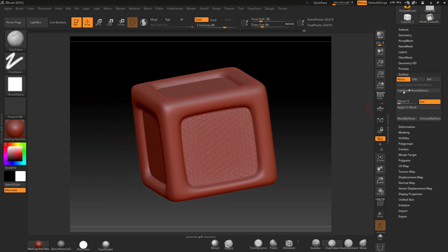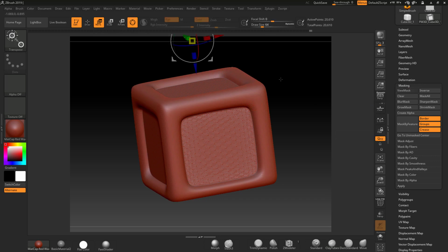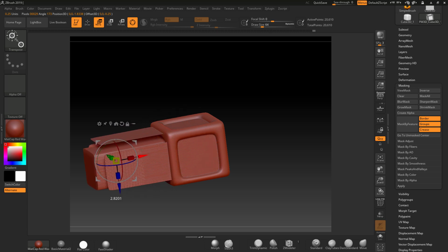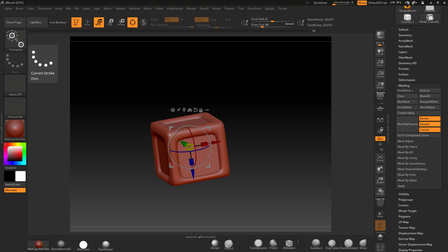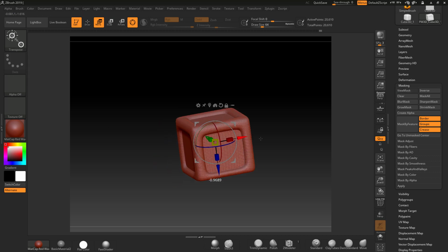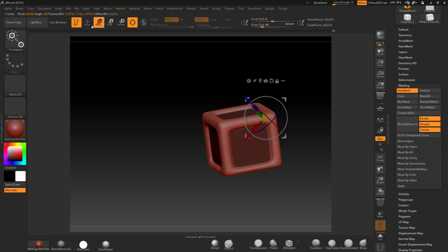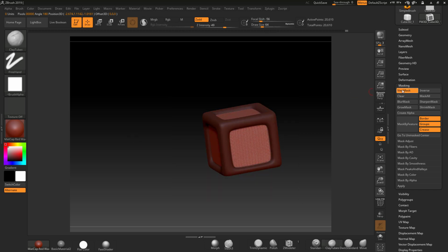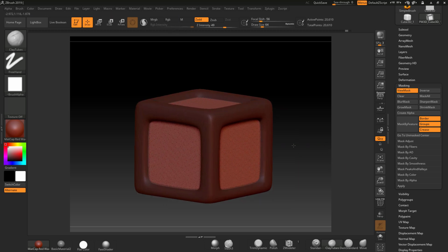But remember, there is a mask on this, and because there is a mask on it, even though you can't see it, if you tried to move it like this, you're going to get a weird thing going on because it's keeping the masked area. So if you did want to move it, you would need to clear that mask, move it, go to Control Shift, remask that area back up. Oh, let's go back to here. And then you turn View Mask off, and then you've moved it. So that is how we can do that masking.